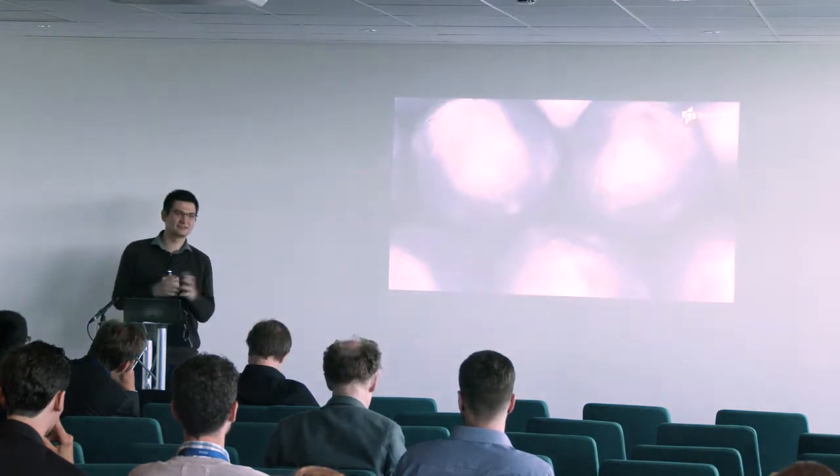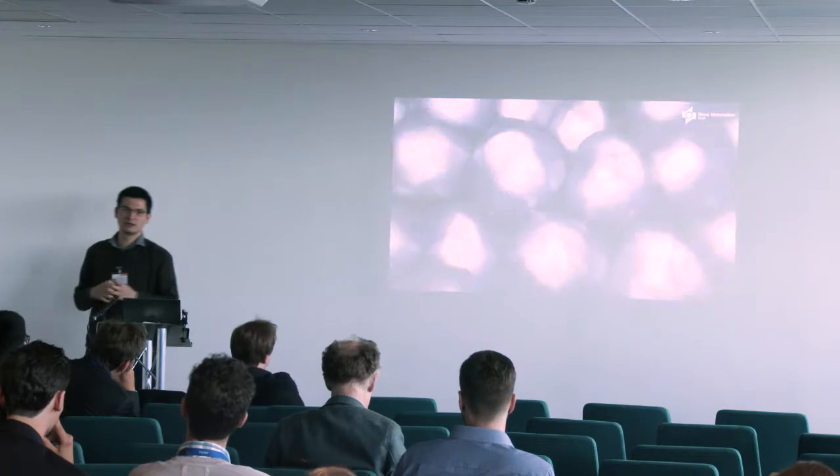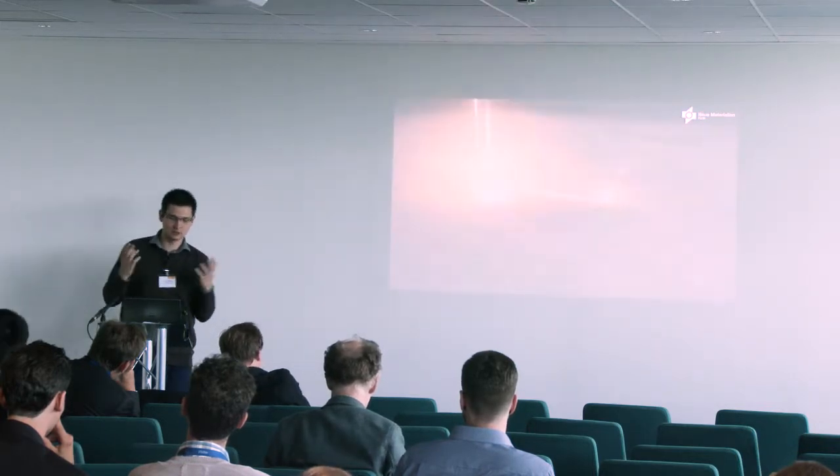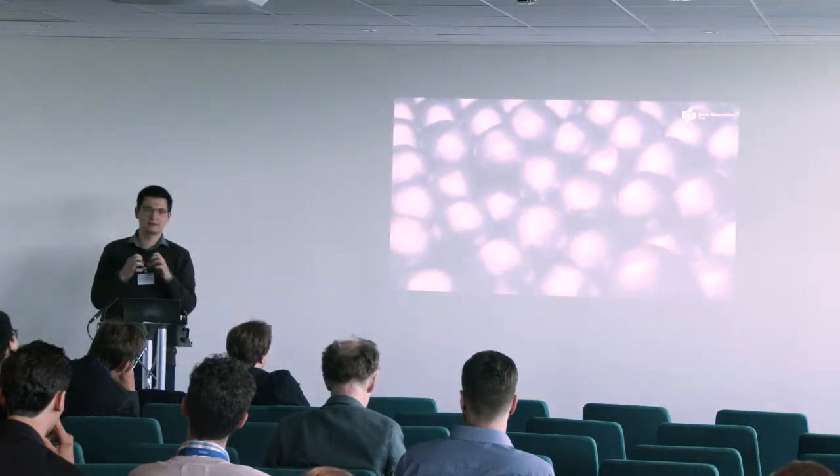So it's a powder-based process, so we build also layer by layer, but we need to sinter our powder. That's because our electron beam consists of electrons, and electrons have electrical charge. So if we overcharge the powder particles, the forces will get stronger than, for example, the gravity force, and then we get powder blow up. So we need to have a stable powder bed before we start melting. This is a crucial step towards a stable process.